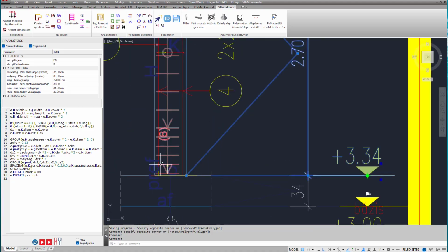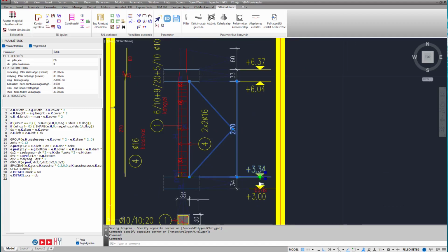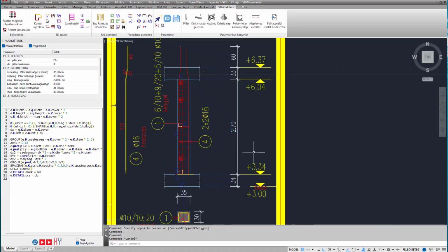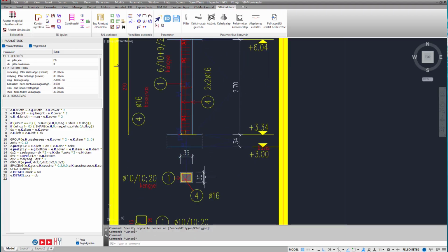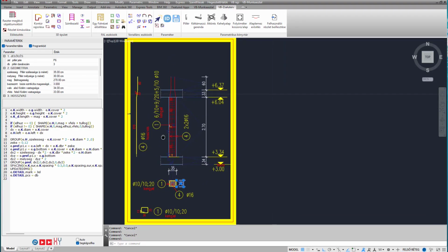Stretching constraints can also be created, for example, so that the lower line of a ladder object always stretches to a given edge of a contour object. It is important to know that these are always polylines, and it also matters exactly which point of which polyline the constraint is attached to. If auxiliary graphics are enabled, the program shows in a faint color which constraints are assigned to each object. In this example, dimensions and level markers are constrained.